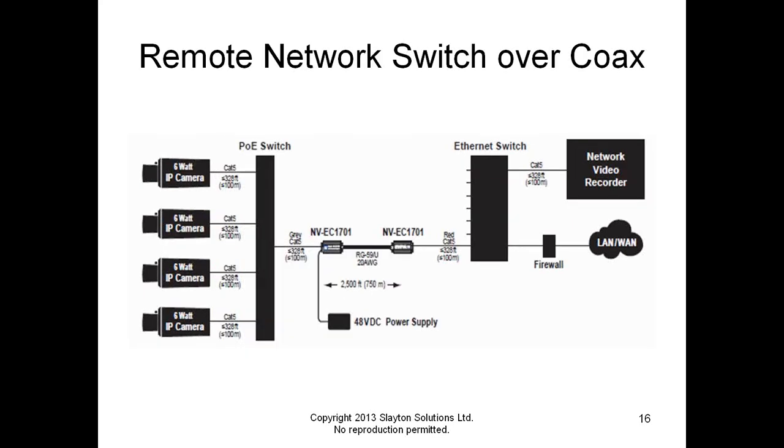And here you see just one more example where instead of connecting a single camera, we hook up a network switch. Power over Ethernet switches can be purchased for less than $100 at ADI or any product distributor. That switch could be connected up remotely, and connected to that switch could be PoE or non-PoE cameras, intercoms, access control readers, alarm panels that are transmitting alarm signals.